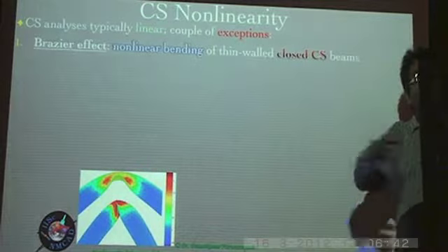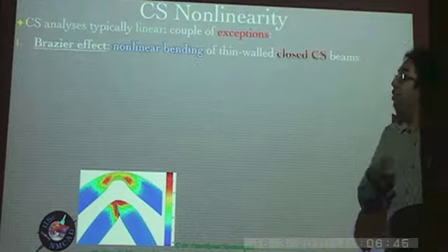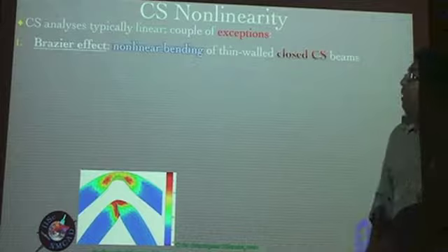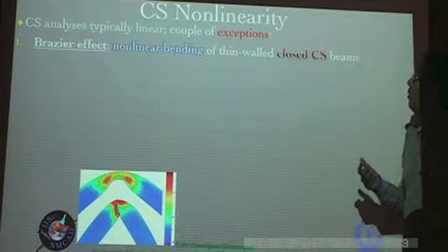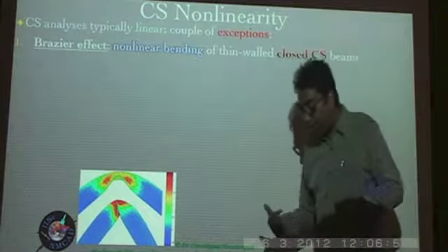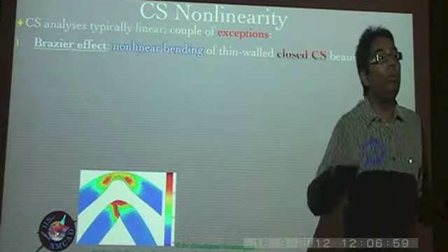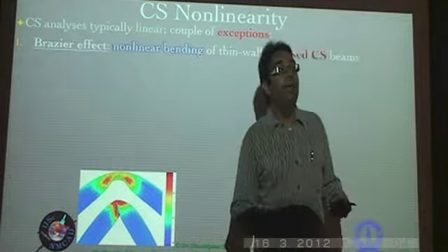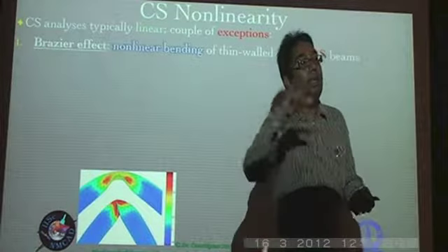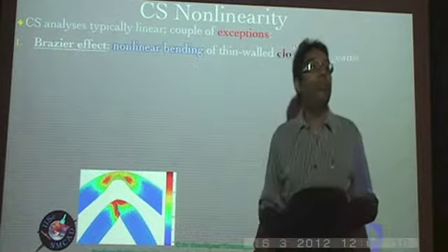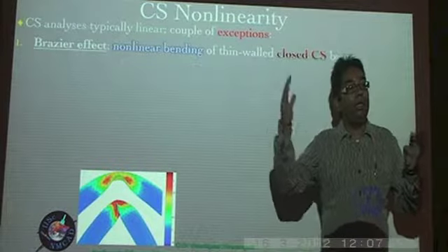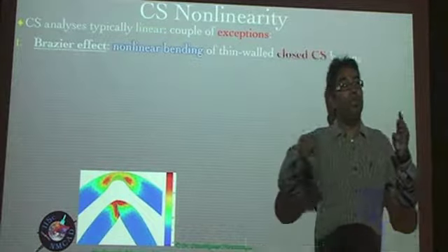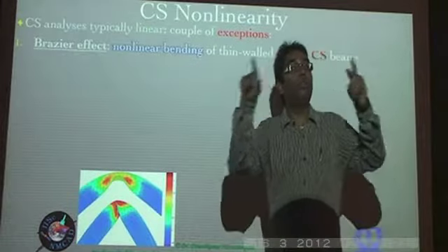Many applications have thin-walled circular shafts, and if they are subjected to bending loads, then this, for example, will become critical. It's not necessarily a circular cross-section. Any closed cross-section, as long as it is thin-walled, will behave in this manner. Even a box beam, which is typically a rough-cut model for, let's say, the interior of an aircraft wing, where you take the front spar web, the rear spar web, and the skin of the top and bottom of the wing to constitute the so-called box beam.